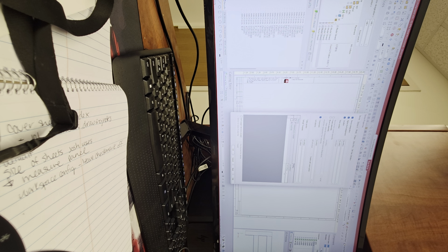So I usually put in 1 just to have some content. But I think even just the presence of the no BOM attribute is sufficient. I probably should confirm that just in my own head to make sure it is correct, but I think just having the attribute should be good enough. So adding this 1 is kind of going above and beyond. It's really needed or not needed. But the no BOM is what excludes these items from your BOM and your reports, as in they don't exist.